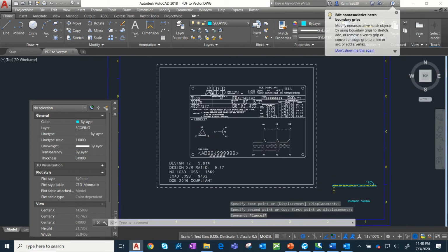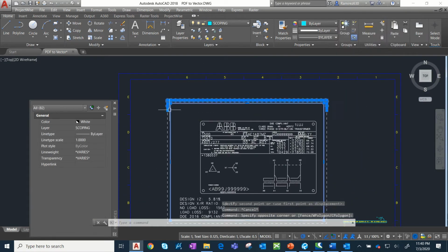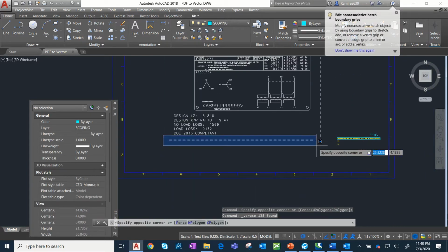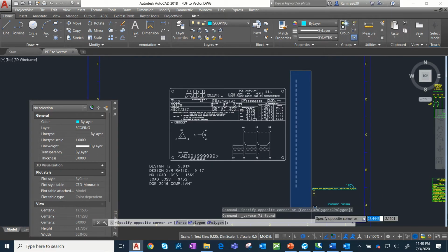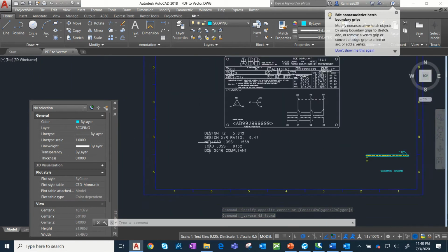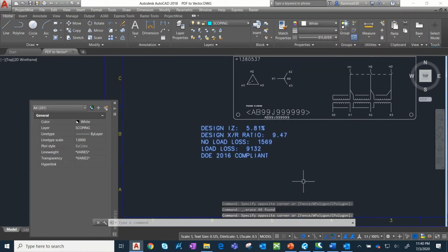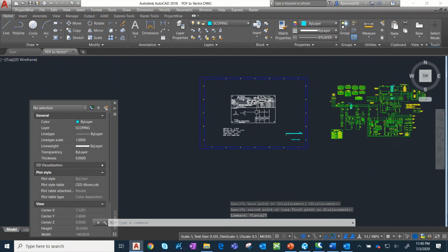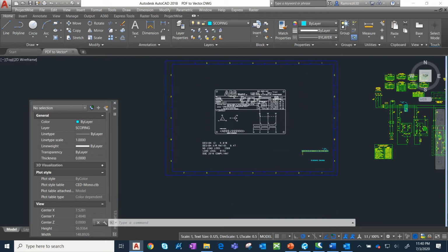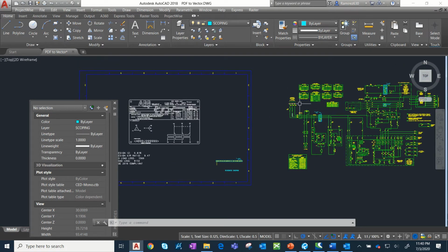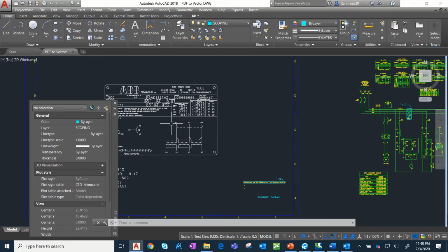For vendor drawings, you guys can just double check with the engineer, but I always delete the vendor border. So now it's in the drawing, but you're not done yet. We're going to be changing the layers on this, so we're going to try to blend it in with what the actual client uses. You're going to take all the stuff in white and make it match, turn it into green and yellow, basically.